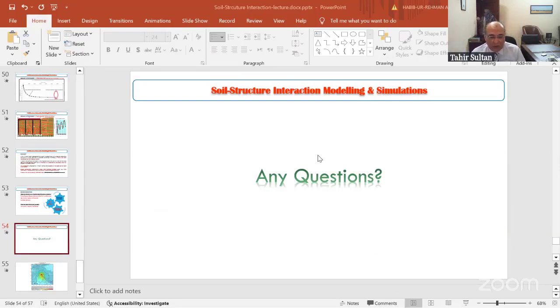The first question is from Rizwan Mirza. I will read the question as it has been put in the chat box. The speaker has shown springs under columns or load points only, but practitioners place springs at a fairly close interval in each direction. This needs clarification.